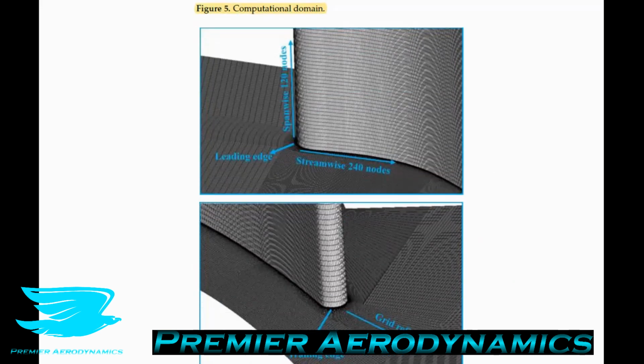So they're saying that they picked the gamma theta SST model, which considers the natural, bypass and separation bubble transitions and can more accurately predict the transition location. So let's talk about these different transition mechanisms. Natural transition is where you have little waves that break down 3-dimensionally and they just transition straight to turbulence.